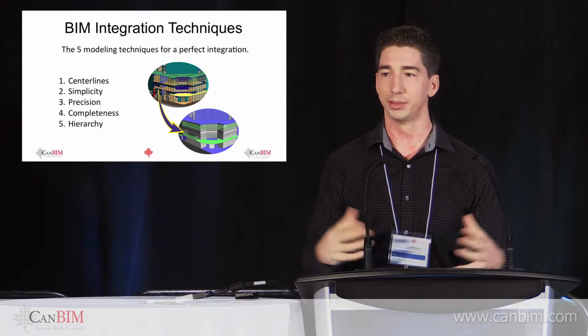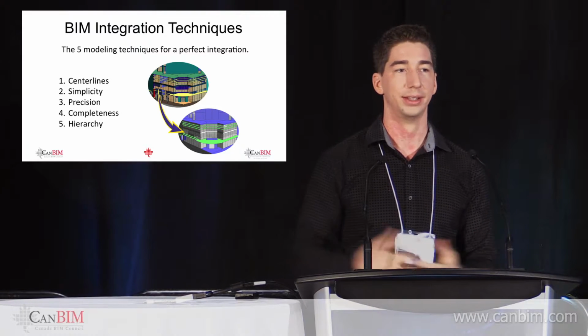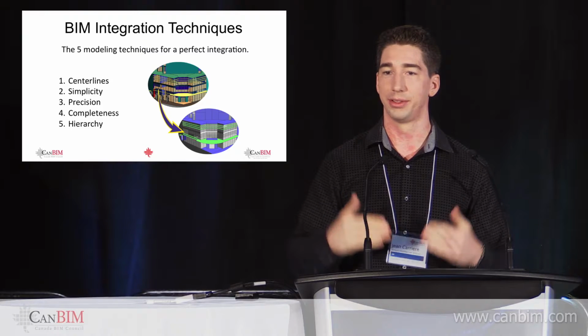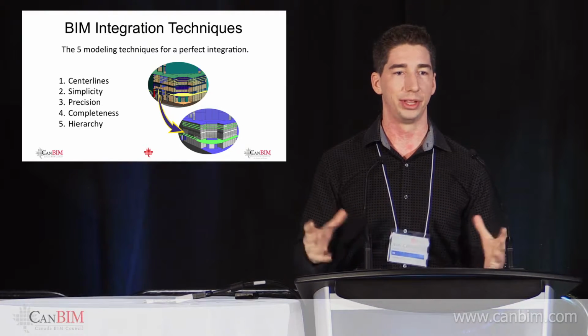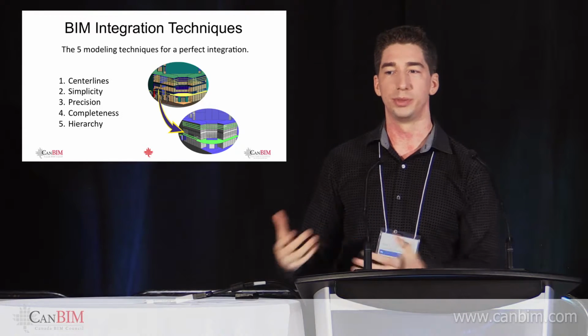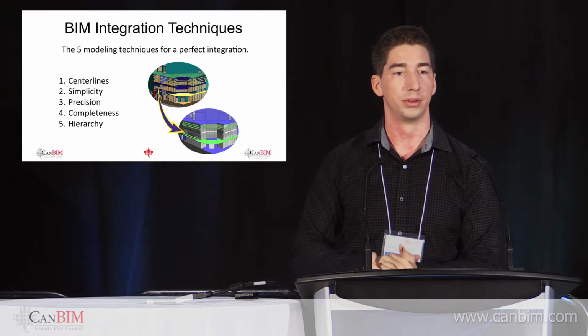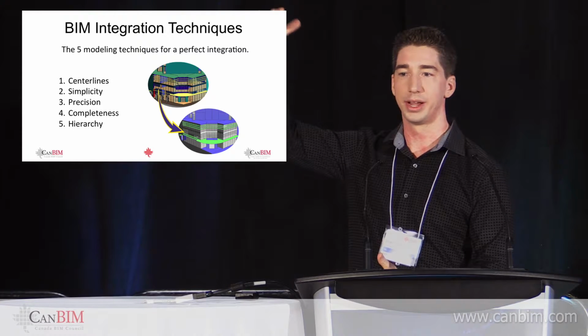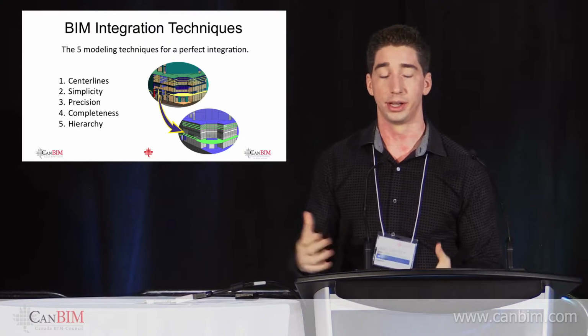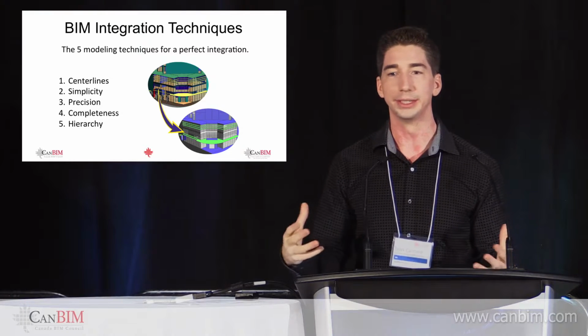There is no look and feel, because what we're doing is exporting a file, a GBXML file. And that file doesn't really care how it looks. It actually just cares how things are snapping together, how thick the envelope is. It's just looking for the analytical perspective of your rooms. So if your room doesn't go all the way up, then it'll recognize that, and it won't actually export the right amount. So everything needs to be complete.